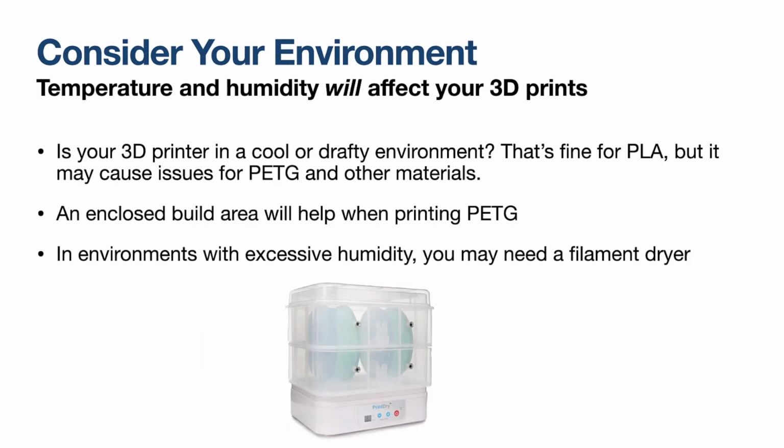This is something that can really impact your print quality and your results. Some materials are a lot more prone to moisture absorption than others. Materials like PVA, nylons, and materials like that pick up moisture very easily. There's quite a few others, but those are some of the more common ones.